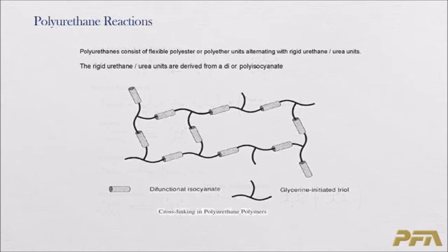So if you think about polyurethanes as a network for the flexible foam, it's a thermoset as opposed to a thermoplastic type polymer, and you have alternating linkages of where the isocyanate was to form the hard segments and the long, flexible polyol chains.